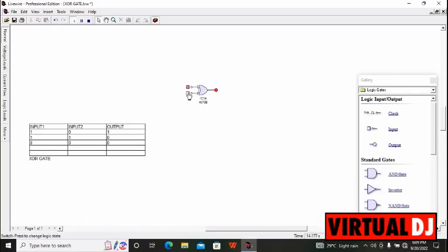But in this case the difference between the XOR and the XNOR is that when both input signals are in the same state, we have 0, we have off state. For instance, both inputs on, we have off state at the output. And when you switch off both, you still have off state at the output. You need one input to be different from the other for you to have an output of on state.